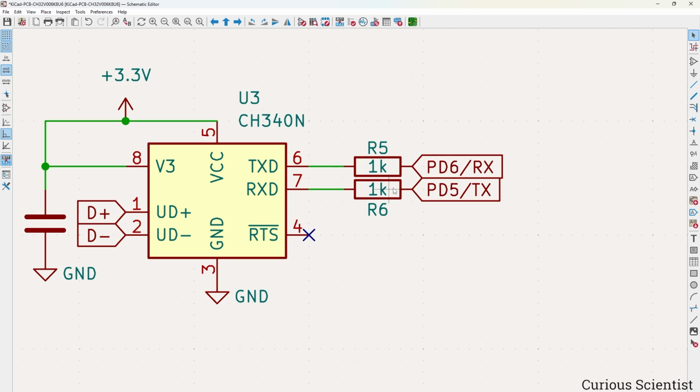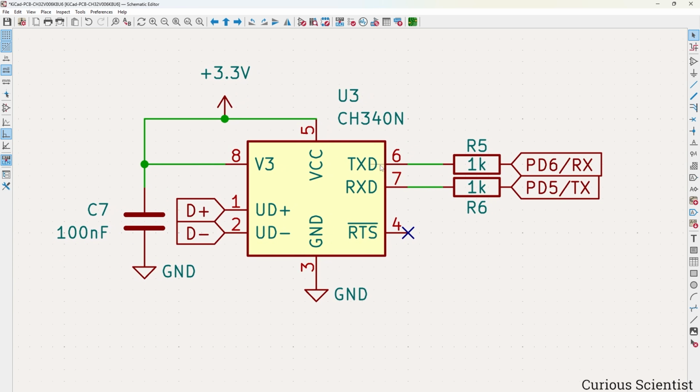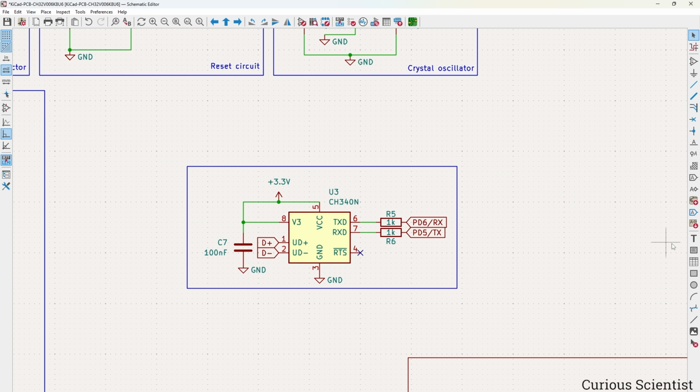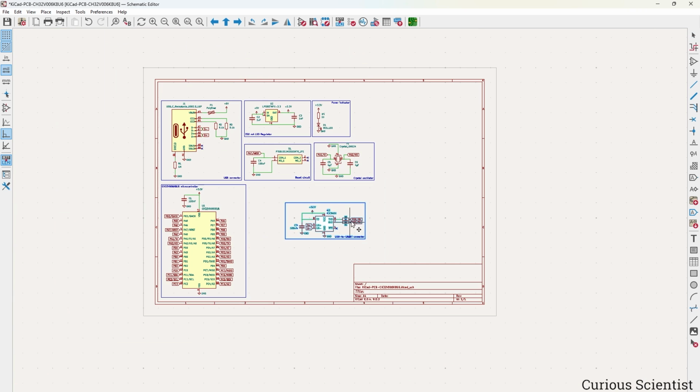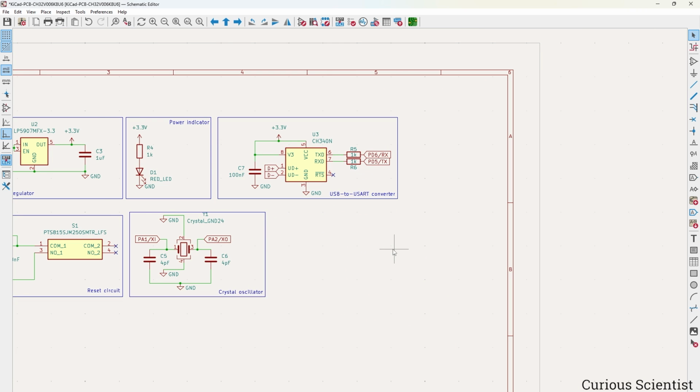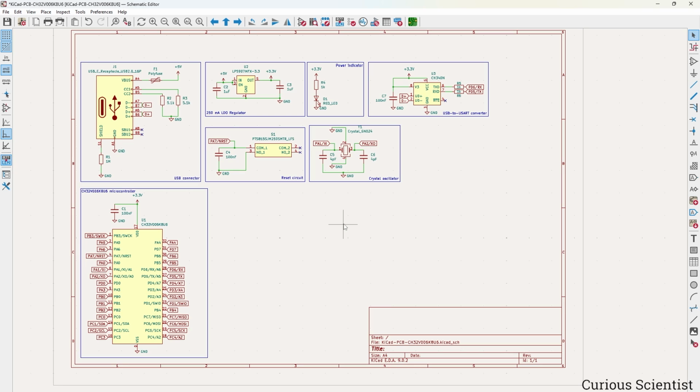So this is it, and with this, we finish this circuit. So let's frame it and let's name it. So it will be this simple. And then let's place it somewhere like this. Then we need GPIOs. And we have, let's say, 2 types of GPIOs. One is the programming interface, so SWDIO or SWIO, however you want to call it, and then the regular GPIOs.